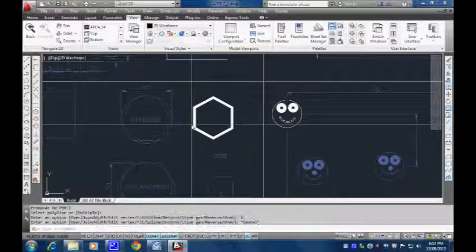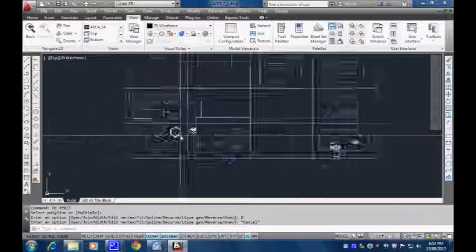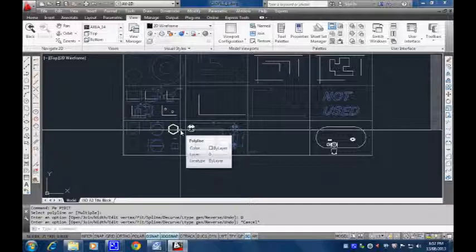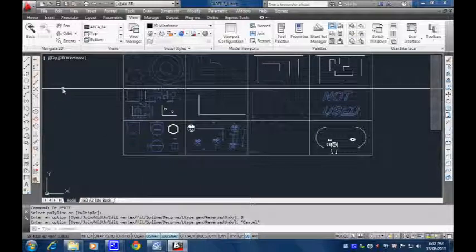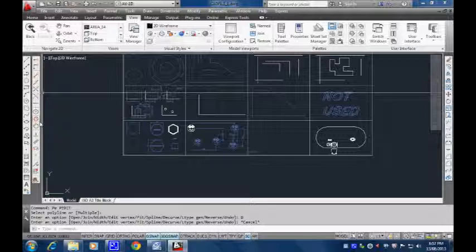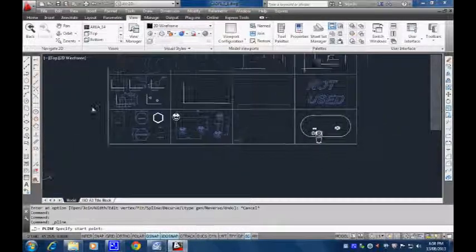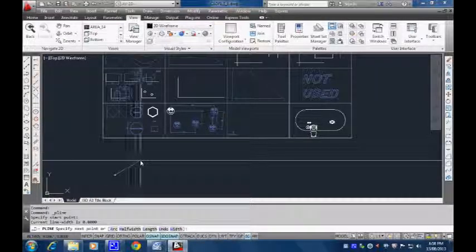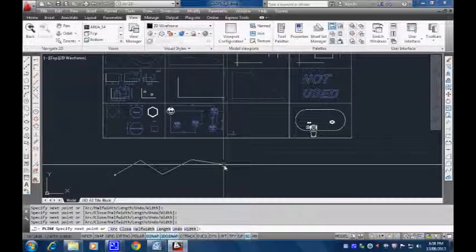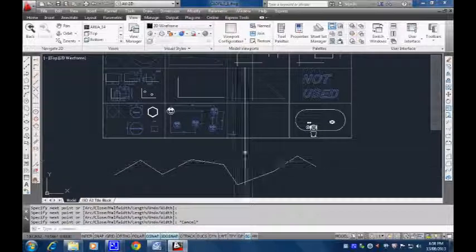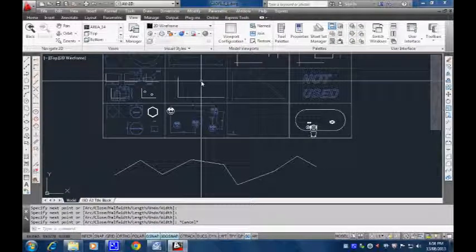Now, okay, polyline. It's basically what a polygon is, a bunch of lines that are stuck together, right? Joined together. So I could just draw straight out a polyline. This one here, PL for polyline, is a short command. Alright, so let's just do one. This one here. Okay, there's my polyline. Alright, it's not closed like the polygon is.